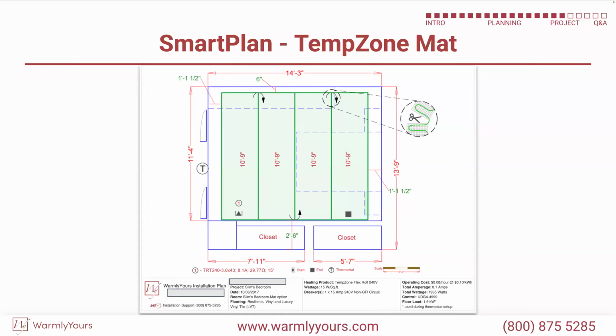You never ever cut the heating cable. You never shorten a mat. You never cut the mat. You never wire two mats together. You never order the biggest one possible and try to just say, I'm going to use half in this room and half in that room, because that's not going to work. We've lived through that multiple times. So you can't do that. You can't buy one big spool and then cut it and put it in different rooms, because then you're in trouble because it overheats really, really fast.